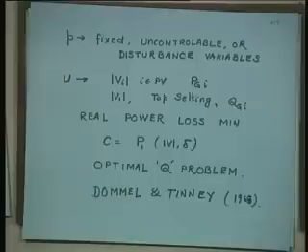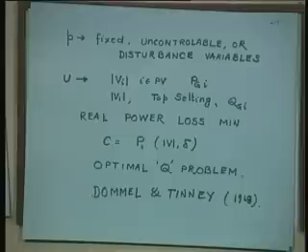What are they? Voltage. You can vary voltage by various means, by excitation, by taps, by SVS, by FACTS. You had a good dose of FACTS last weekend. And PGi, power generation, is controllable by controlling the steam. You must have had a heavy dose of AGC when Dr. Bhatti is teaching. AGC means the steam input can be controlled, or the water gate opening can be controlled. So, PGi can be a candidate for a control variable.